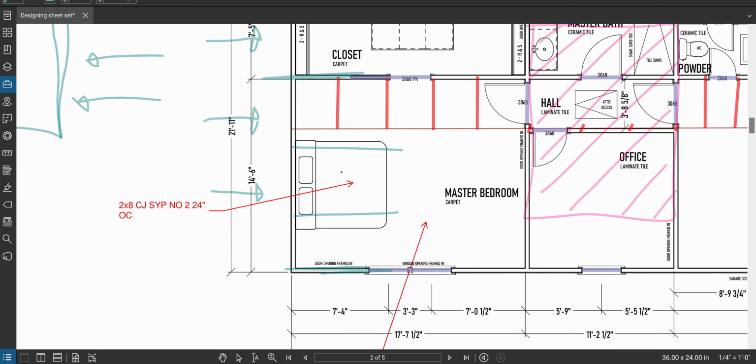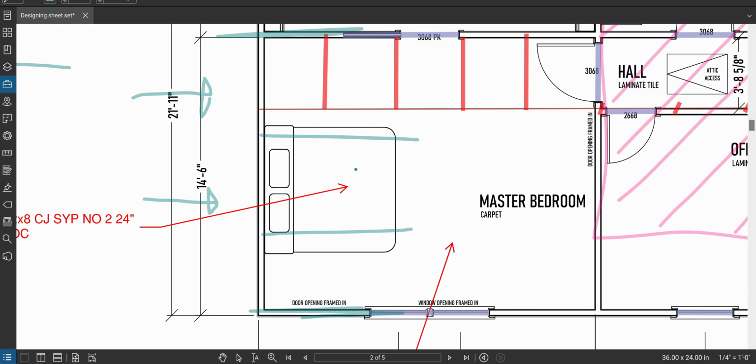The way I'm going to do this is there's a detail in the Wood Frame Construction Manual from the American Wood Council on how to add blocking in the ceiling joists and strap it to the wall so that you can support this wall. You're going to add a block between each ceiling joist, some distance back into the wall, specified by the table in the book, right? You're going to add those blocks in. And then when you get to the wall, you're going to take a metal strap and run it from the blocks down the wall vertically onto a stud. I can't show it on the plan view, but it runs down vertically.